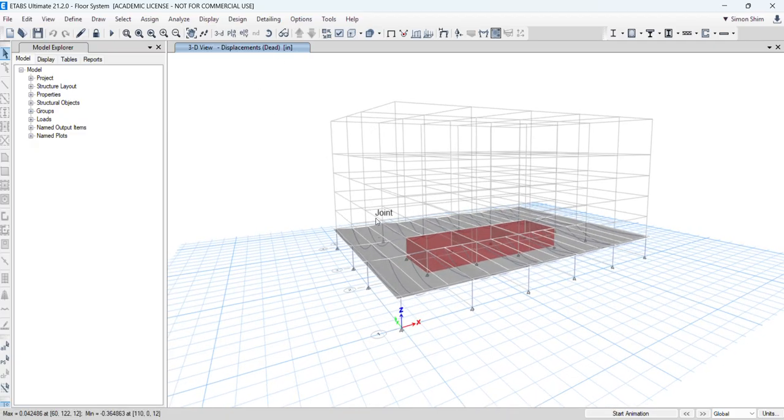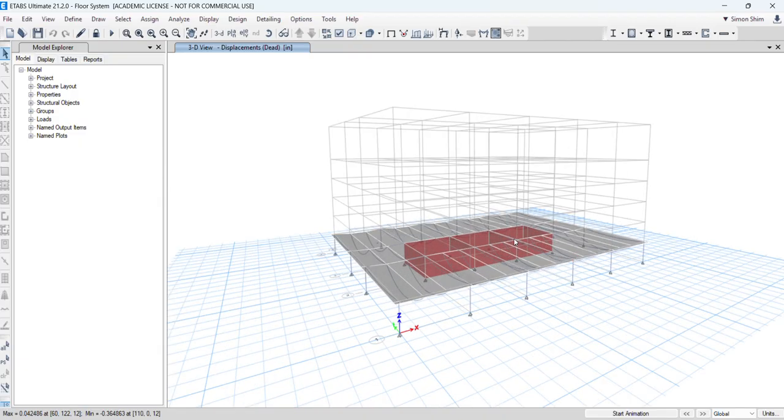The dead load is the self-weight that is loaded. The beam deflects vertically down. The slab also deflects vertically down, right? So it's kind of common sense. You should always double check when you assign, and the loading and all your model should behave based upon your expectation, right?